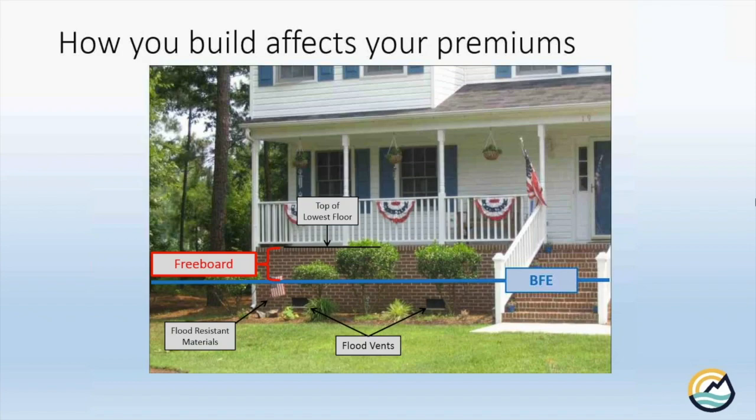But let's say something goes wrong. Let's say either the builder, when he's putting this together, forgets to put the flood vents in, or me as a property owner not knowing any better, I go and block up or take out the flood vents. Well, what happens then? The insurance agent is going to come back and say, okay, well, those flood vents are gone. You could have something happen to your foundation. So now your lowest floor is no longer up there where your living room's at. It's down here where your crawl space starts. That's where your risk starts.